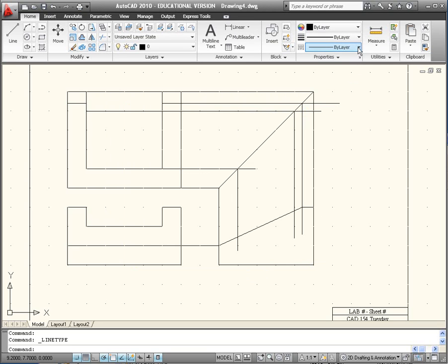And then up here you can scroll down and select hidden two as your line type. And we're going to put in our hidden line, which will go from here past there. It's not on an even snap, so it makes it hard to pick up. And then we're going to put in another one, turn my snap back on, from here to there.